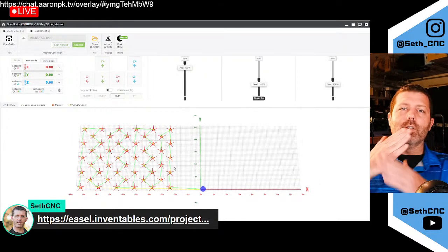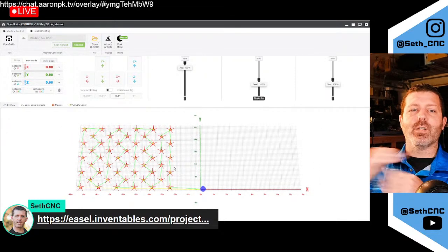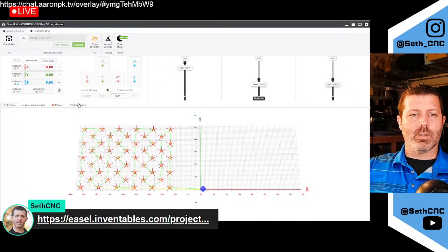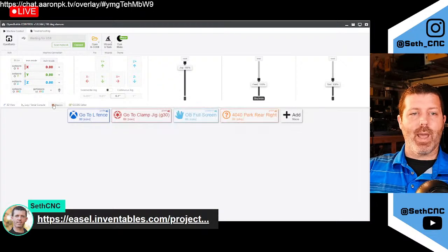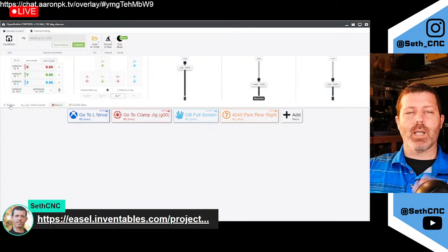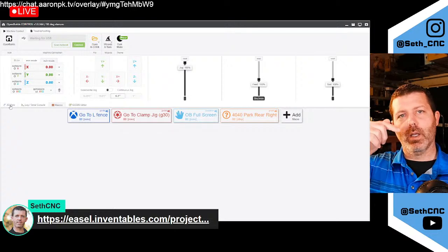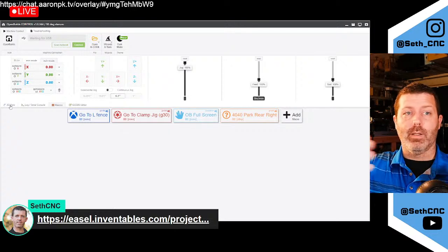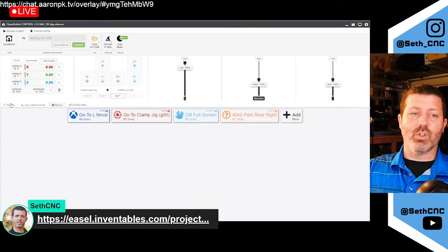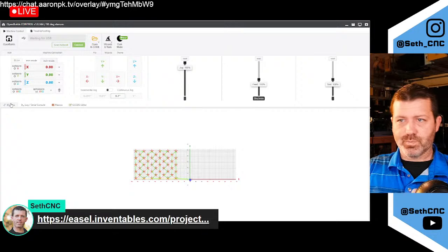So I talked about doing the X pattern to find the center, but we also talked about the macro where you could identify what the side is of the board and jog over, and it will save the center automatically as the X and Y zeros within OpenBuilds if you set up that macro. Those are just 2 different options for finding center.